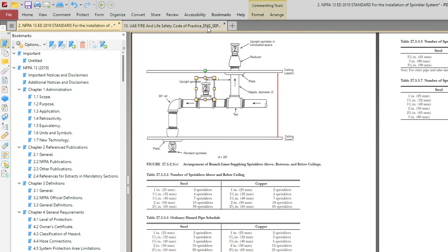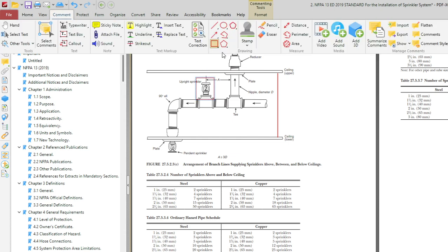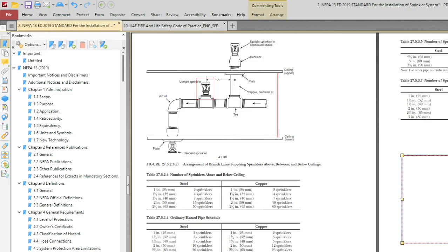See, for example, if I have a big building, I have a feed pipe here, then I have multiple branches, and I have a sprinkler, a sprinkler, a sprinkler everywhere. But what is my basis of design? I will be protecting 1,500 square feet only. That's it. I'm not going to calculate for the entire floor.